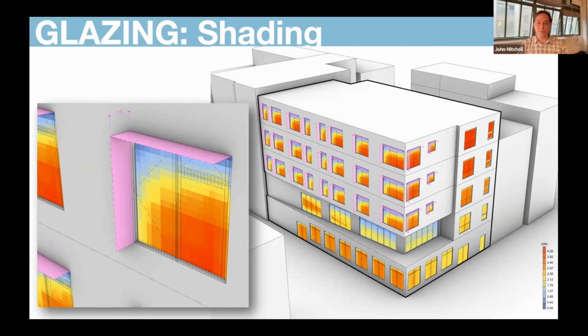and we don't want all those extra solar gains as we might in a different typology. And so we're suggesting some shading that will actually bring down our cooling and also bring up our heating. So it's a balance. We have to give a little bit of heating away in order to bring the cooling down. But that's the game. That's what we're doing when we're designing Passive Houses. That's how we're weighing in as consultants in these early design meetings with our Passive House teams.